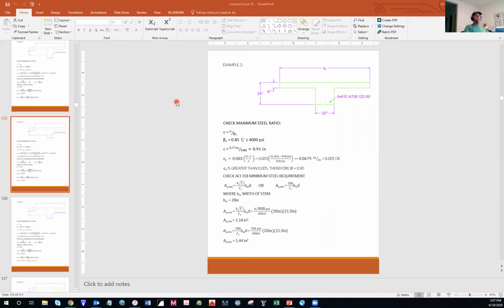And so in the example where we have a beam with skip loading, I think it would be more instructive to go through and draw a shear and moment diagram for each one of the skip loaded cases that I've listed. And when you do that, see the difference between using a table and drawing a moment diagram is when you draw the moment diagram, you get the whole picture. And I think for that case, that would be more instructive.